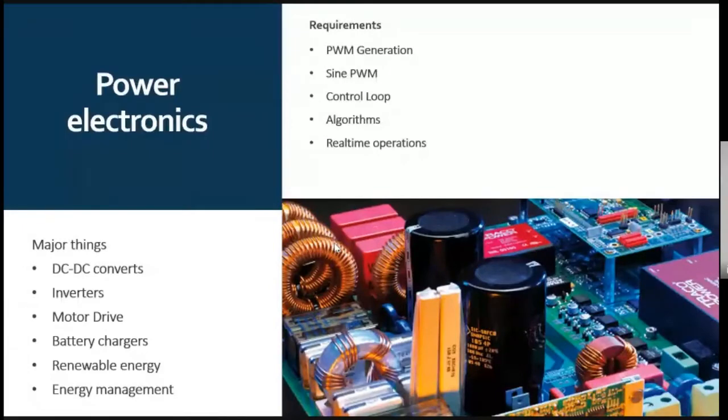Let me just discuss about power electronic circuits. We know that there are a lot of power electronic circuits, just like DC-DC converters. In DC-DC converters, there will be switching circuits, MOSFETs, inductors, capacitors, and so on. The role of microcontroller is when it has to be controlled, just like an MPPT, or just like a programmable power supply, or a grid interactive inverter or something. In that case, there should be a programmed logic, or there should be a closed loop control system. In that case, we should have a controller, a programmable thing. Here, I am proposing a microcontroller or FPGA.